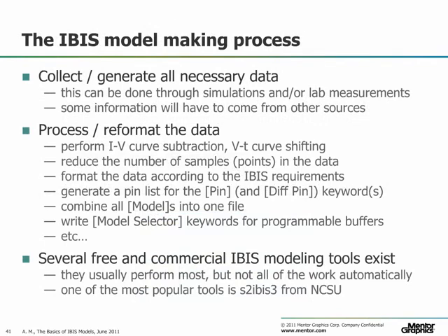After learning about all these technical details, you might wonder how you are actually going to sit down and write your own model. First, you have to collect and generate all the necessary data for your device. This can be done through simulations and/or lab measurements. But not all of the information that goes into the IBIS file can be generated from simulations or lab measurements. Some of the information may have to come from the data book or from the specification of the device.